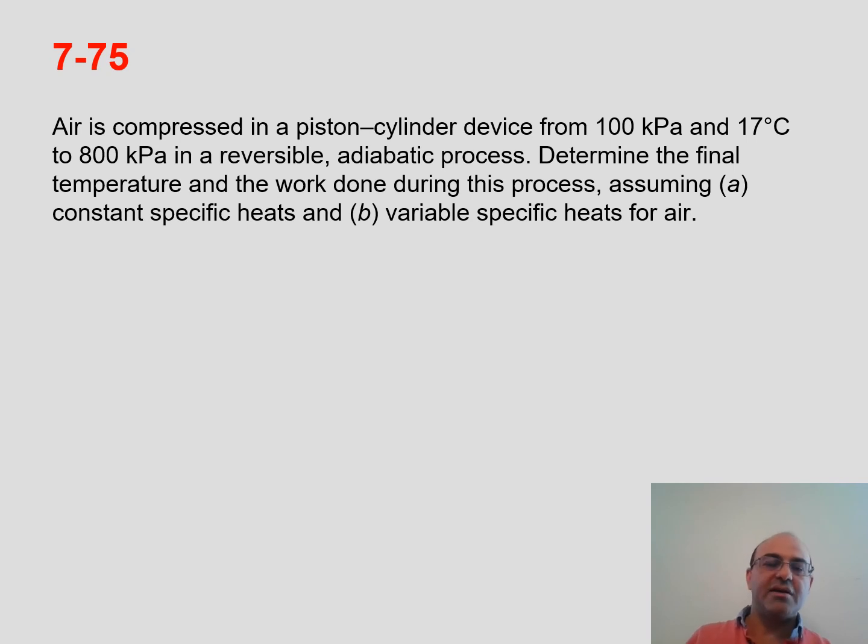All right, so another problem, 7-75. Air is compressed in a piston cylinder device from 100 kilopascals and 70 degrees C to 800 kilopascals in a reversible adiabatic process. Reversible adiabatic, so it's isentropic. Determine the final temperature and work done during this process.